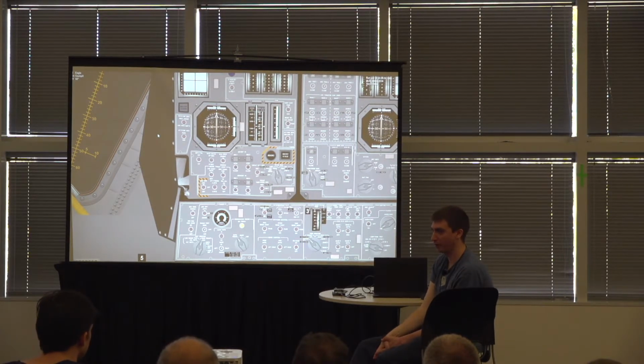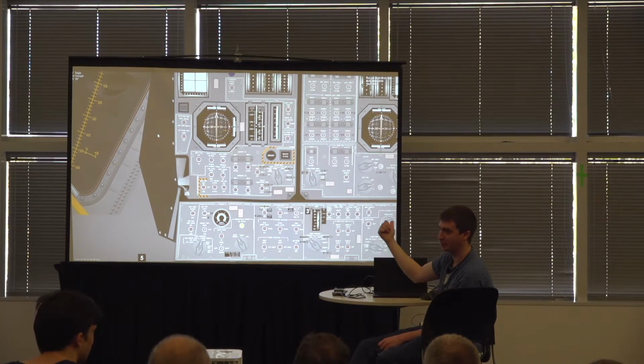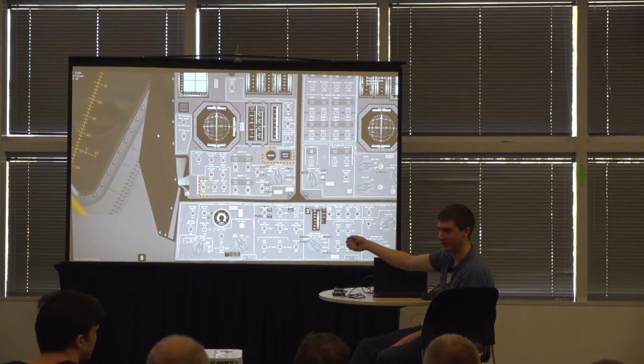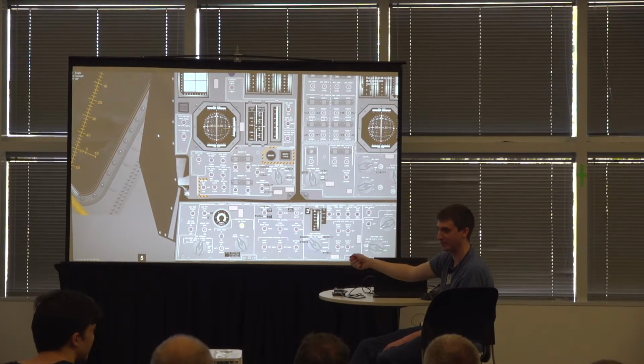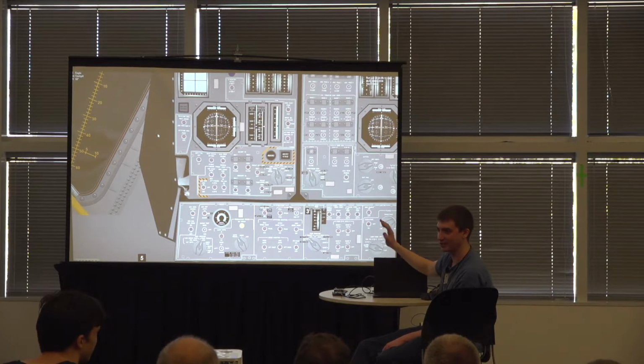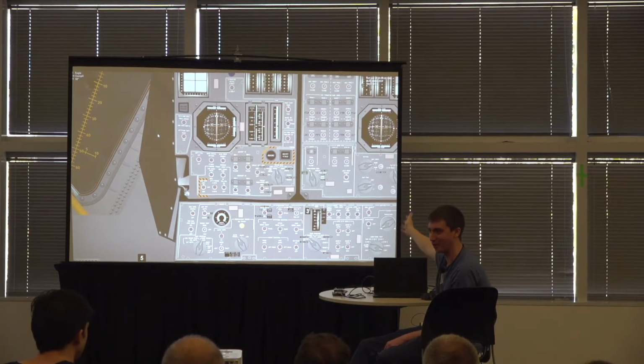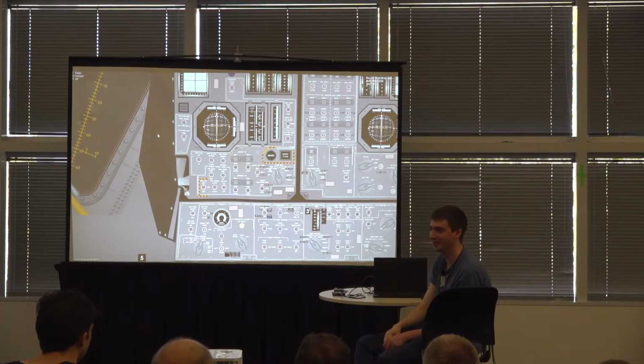There were four 1202s, one 1201. The first ones they got were in Noun 68. I didn't get those because they actually got a little bit lucky on Apollo 11, because Neil Armstrong had a policy against doing the redesignations in Program 64. The redesignations don't really work when you have enough overload to get the program alarms in P60 or in Noun 68. So I made the trade-off to get the alarms in Program 64, but still have it be functional for the demonstration.